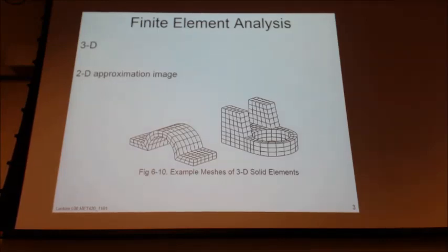And like we did in 2D, we want to try, if we can, to take advantage of symmetry when we're dealing with 3D, to cut down on the processor time. And I think we were able to prove with the 2D that the symmetry gives us a pretty good approximation of doing the full model. And we can often get to the solution quicker with the symmetry than we can with the full model.